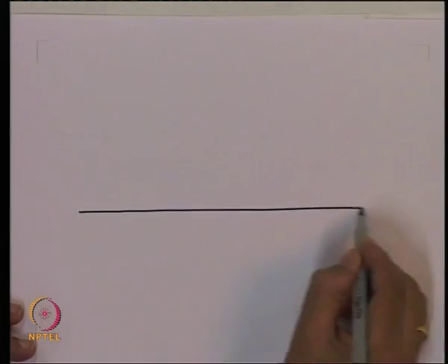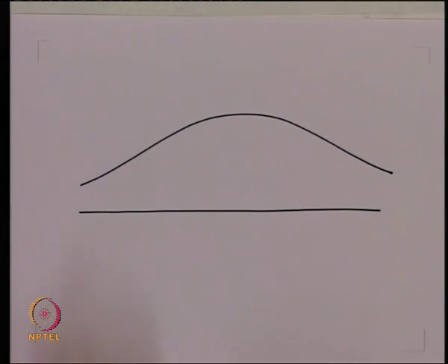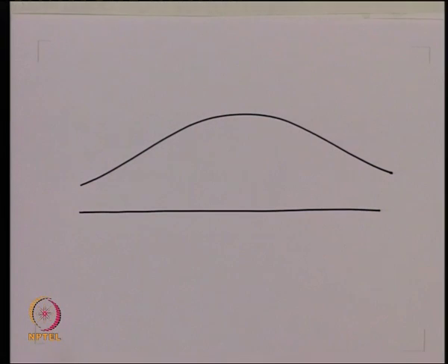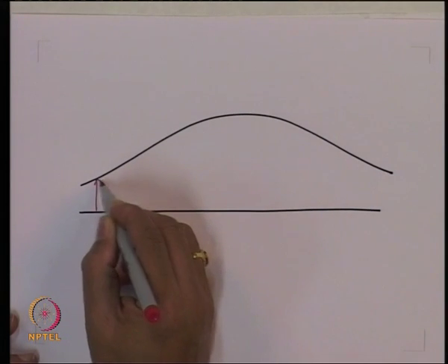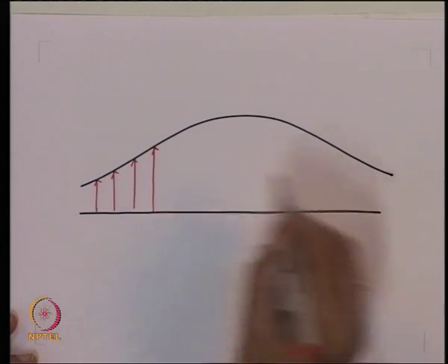So, what we can say is that we have an intrinsic carrier which has a spectrum like this, and that is the carrier we want to modulate by amplitude modulation, or simply we want to change the envelope of this total light, which has a spectral width of about 100 gigahertz. So, this can be visualized as if I am transmitting multiple carriers simultaneously, all up to this.